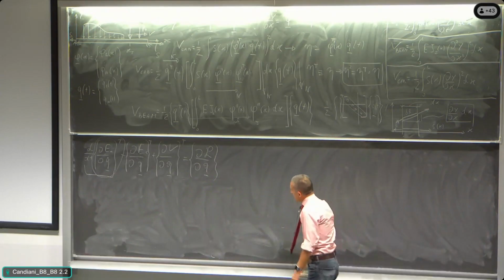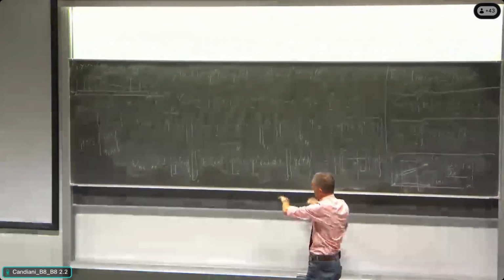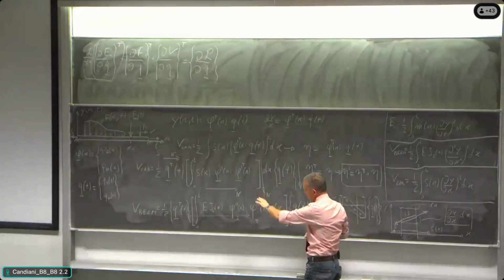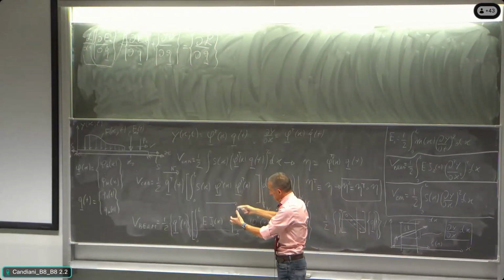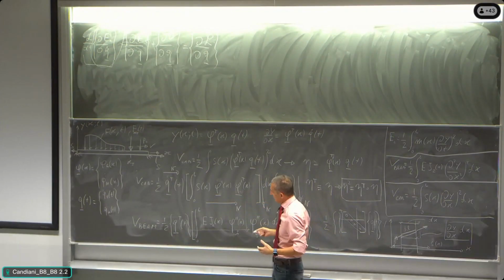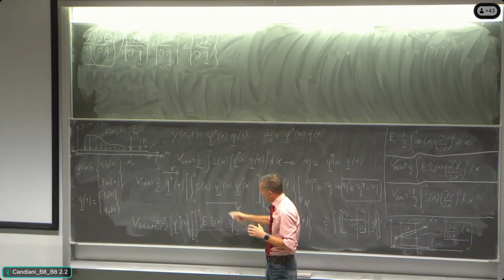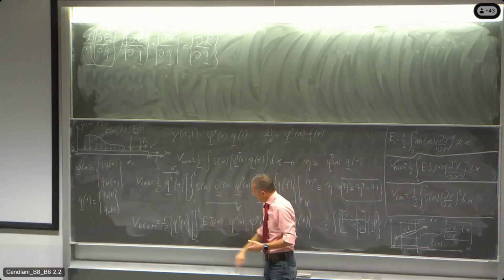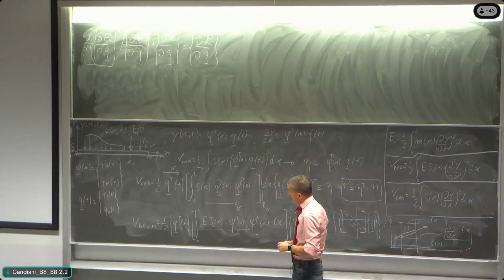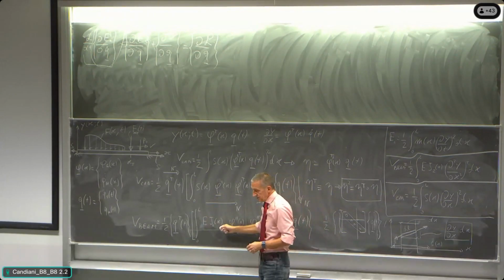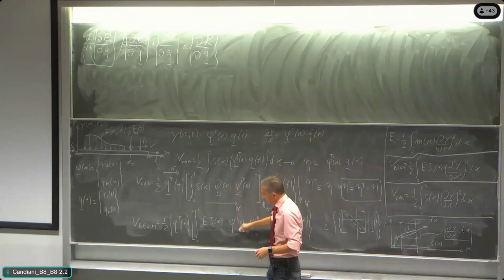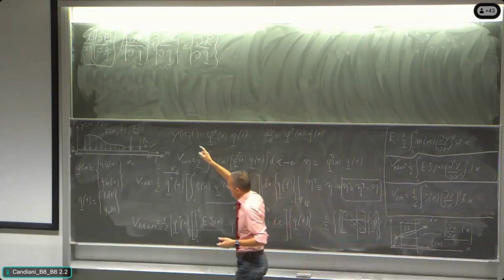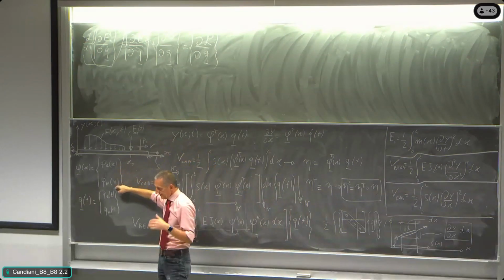Finally, having defined those mass and stiffness matrices that come from the quantities defining the problem, such as the axial action, in case it is the tension of a cable, the geometrical and inertial quantities of the beam, and the first order and second order derivatives of the eigenfunctions, where the eigenfunctions are the solutions of the free motion of the problem.